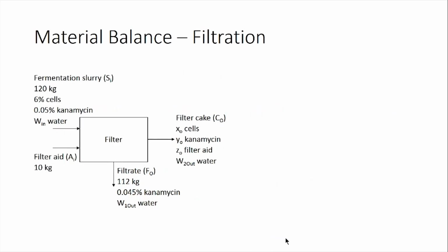Here is the flowchart which we drew, in more legible fonts. Now let us start with the balance equations. The first balance we write would be the total balance. The total balance equation for this system would basically be input equals output, because it is a system in steady state, leading to accumulation being 0, and as the system does not have any reactions happening, generation and consumption terms will also be 0. So input equals output.